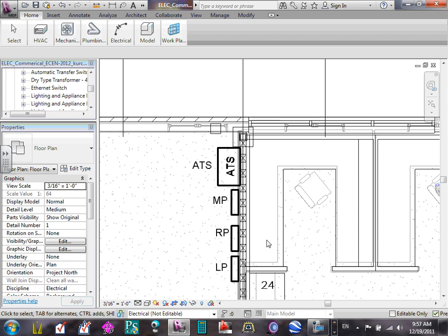Okay. We have an auto, by the way, Phil, if you're looking at the projects that we did before, again, we did it differently. This time we decided to back up the building completely on auto transfer switch from the get-go. So that's why, and we picked an auto transfer switch that we can size from 400 amp all the way to 1,000 amp. Ours is going to be 500 to match the panel, most likely. We'll adjust it later. Cool?